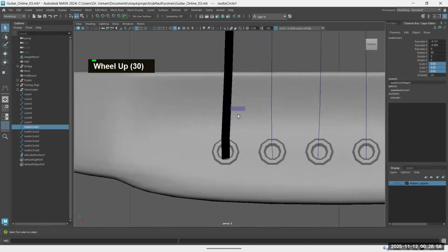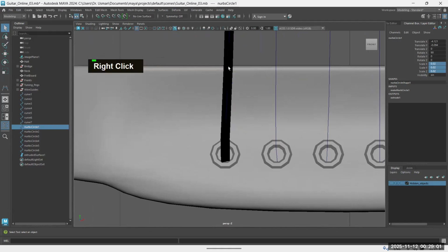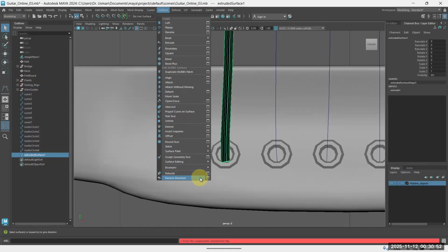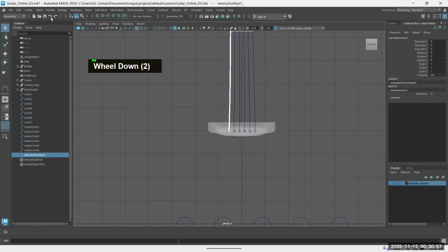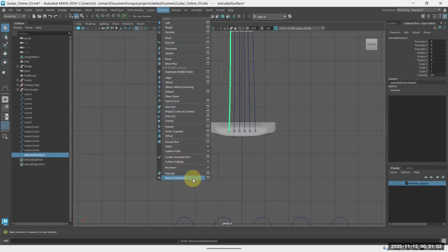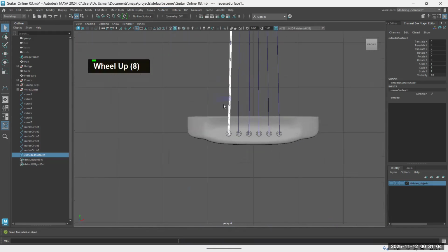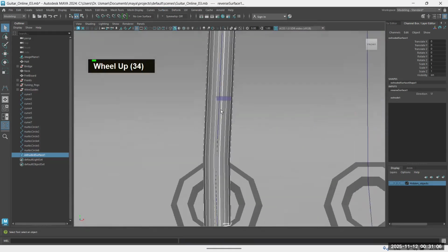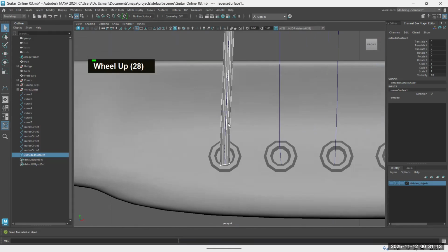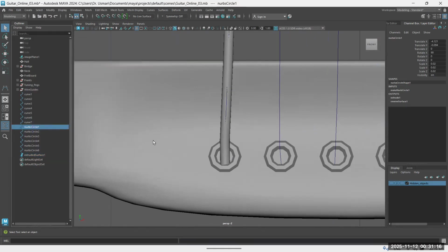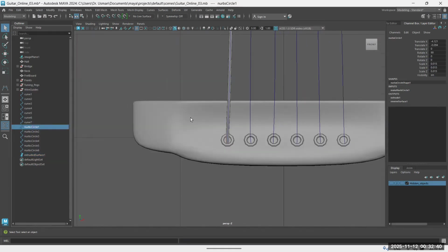But you see, I need to select this one, reverse direction. So what we do here, we select this one and we go to the surfaces, and last option is reverse direction, so that it flips the face and back pass on the first surface. Just change that. So I suppose this thickness is too much, so I will select this first circle and set 0.015.